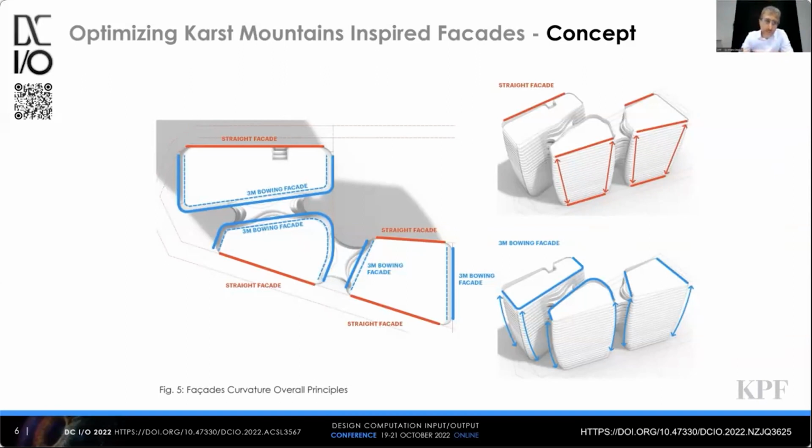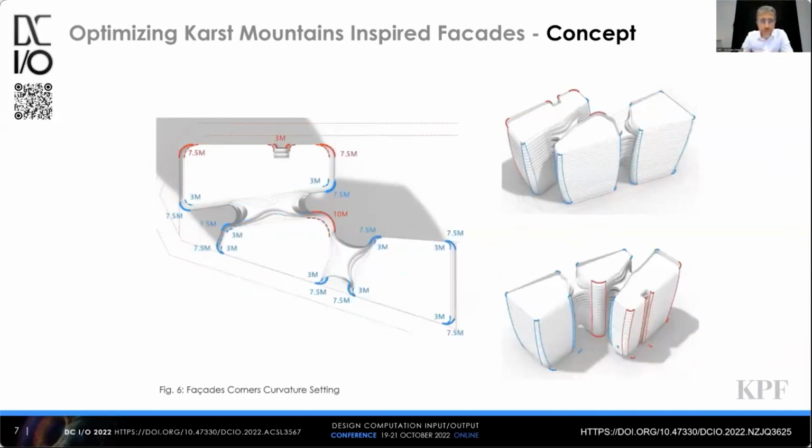And that bowing out and tapering created a really interesting play, but also complication that we had to resolve in terms of geometry. And notably, the key complication came from the corner radius that changes as you go up. The idea was that this building is not a high building, it's a 100-meter building, and this bowing out and tapering gives it a bit more verticality. And so some corners were tapering from 7 meters to 3 meters, and some corners from 10 meters to 7 meters. And so that created different instances around the building that we had to resolve.